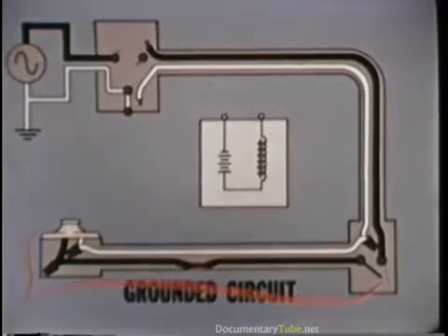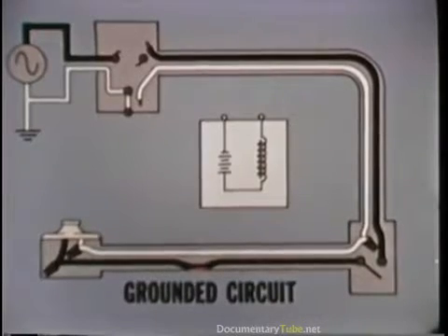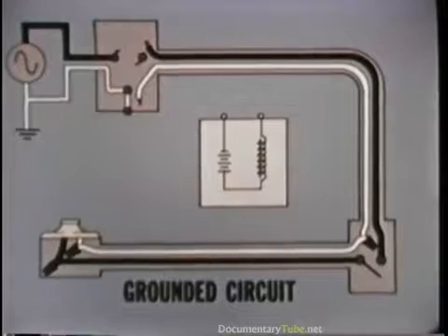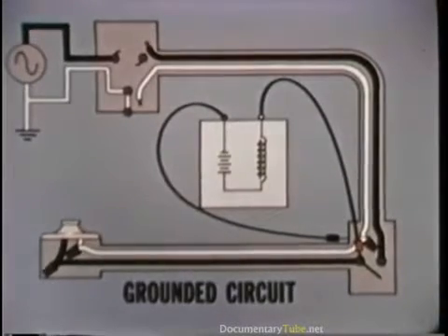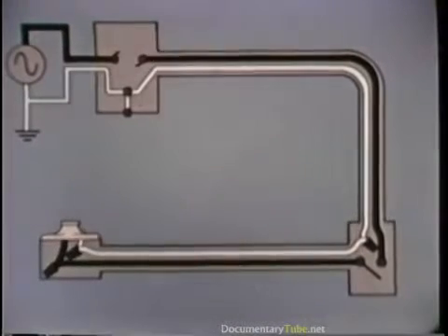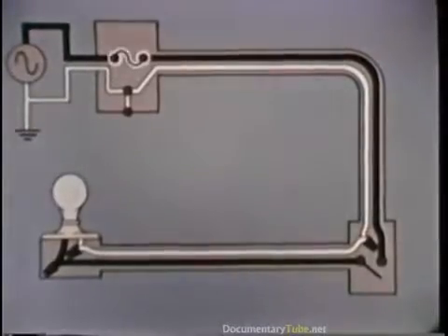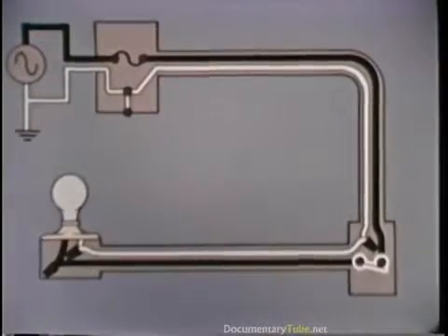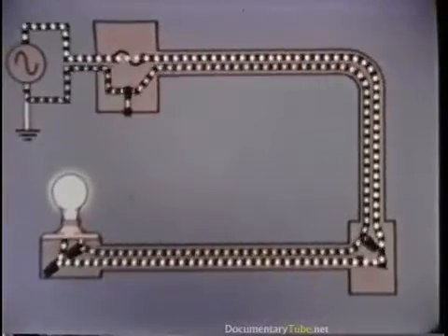In a longer circuit, the diagnosis would be confirmed by checking the next connection. The ground is removed, and the circuit is retested at the trouble point, and all connections are restored. The light and fuse are replaced, and when the switch is turned on, the circuit is back in service.